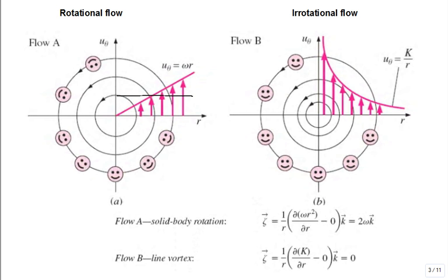You can take a look at hypothetical fluid flow fields. Here's one. They describe the velocity in the theta direction. So here's your r, and at any point, let's say along this line, the velocity in the theta direction is perpendicular to the r direction, and there it goes, and you can see the profile. As you get further out from the origin, it's linearly increasing.